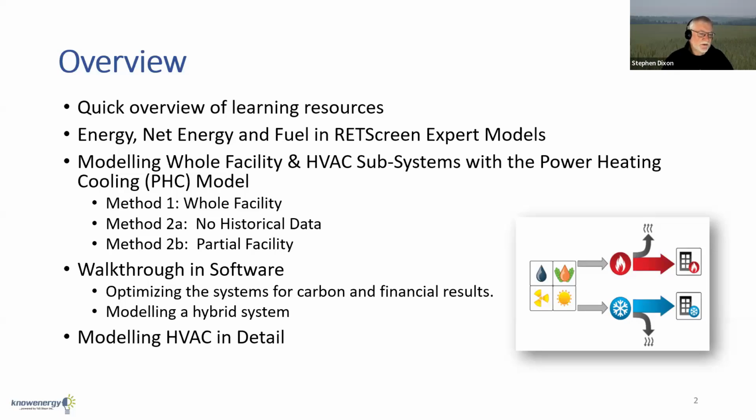Adam will take us through a couple of examples, the whole facility doing this, or where you have no historical data, using RETScreen to model a building. Maybe you're part of a campus and you have multiple buildings, but you don't have a meter on a building. So you want to electrify that building. So how do you do it? Well, you model the entire building, generate the bill as it would be, and then use that in the other tool, the power heating cooling model, otherwise known as the PHC model today.